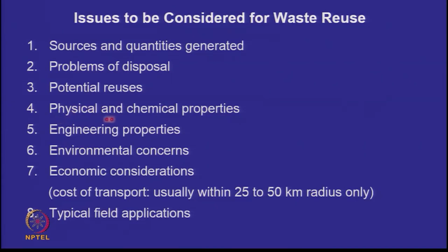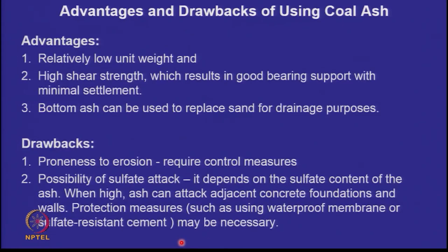We have to go through intensive physical and chemical testing. We have to look at the engineering properties. We have to address the environmental concerns of putting that material on soil. We have to look at economic considerations. Typically up to 50 kilometers away, now you can bring in all these waste materials if they are being given to you free of cost, and the material will be cheaper than the local soil, and then you have to see which applications they are useful for.